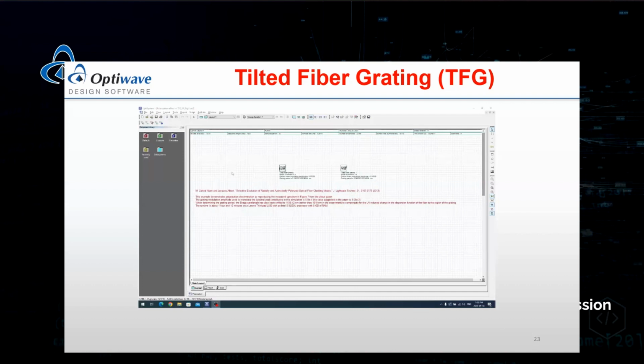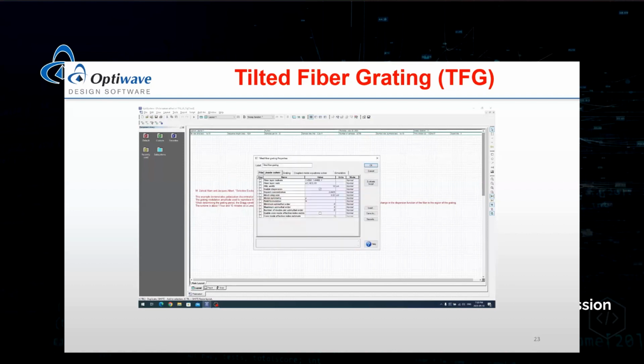Before running the simulation, you'll have to specify a number of parameters relating to the optical fiber, the mode solver, the grating, the coupled mode equations solver, as well as the location of the output files for the transmission and reflection amplitudes. For the optical fiber, the layer indices as well as the layer radii will have to be provided by the user. The user will provide these values as a string.